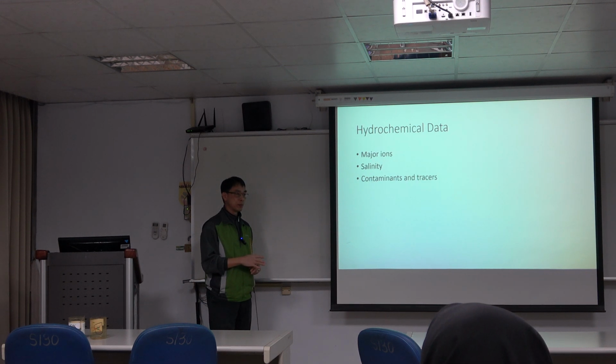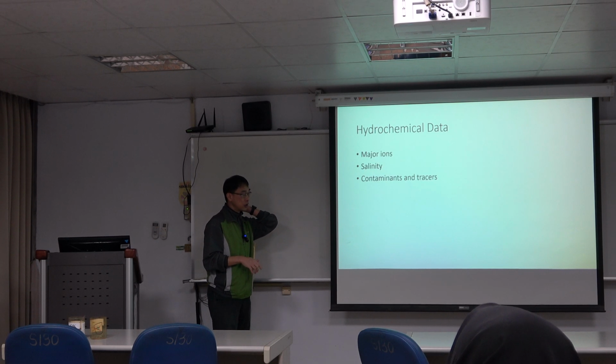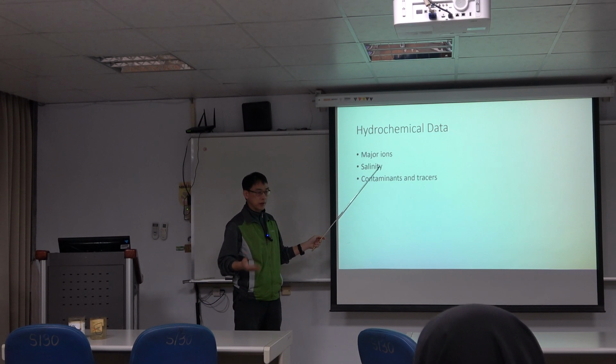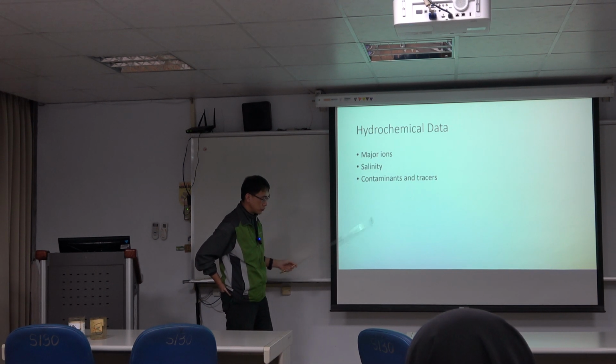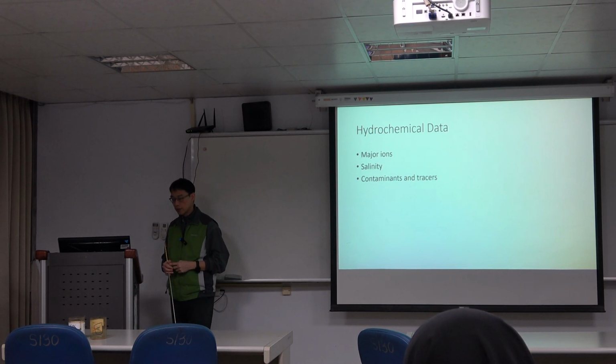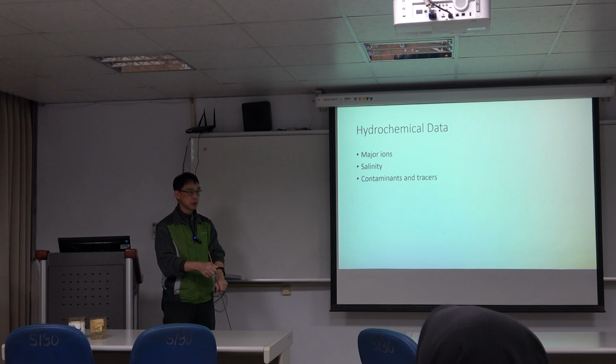And that will be a very important part, because if they are from the rainfall systems, that means they are easy to be replaced, and they become more sustainable to use. But if they are from paleo waters, that means they might not have a sufficient water source. And after you use that, they might go dry, and they will not be able to be used sustainably. So that will be a very important part to understand the source, using the major ions. And salinity is the issue for seawater intrusion. In the coastal area, if you have higher salinity in the groundwater system, that means they might have intrusion from the seawater.